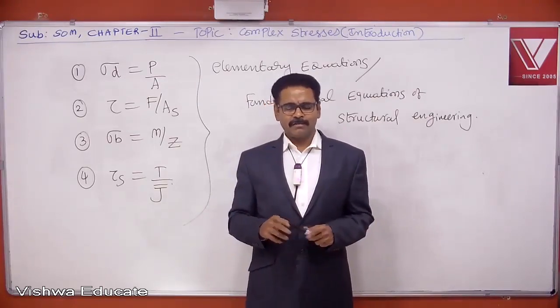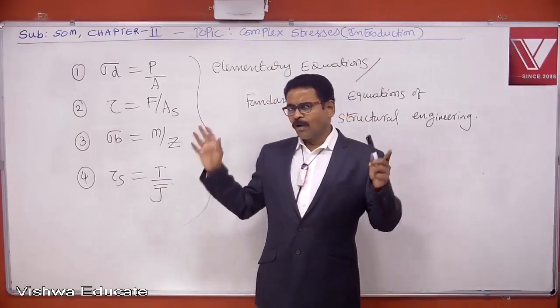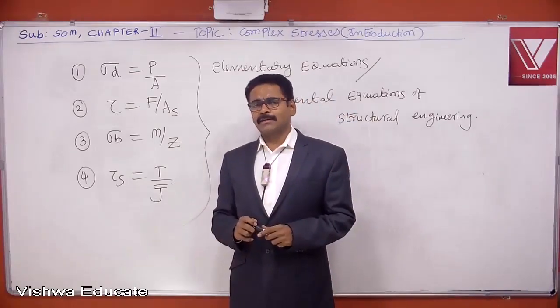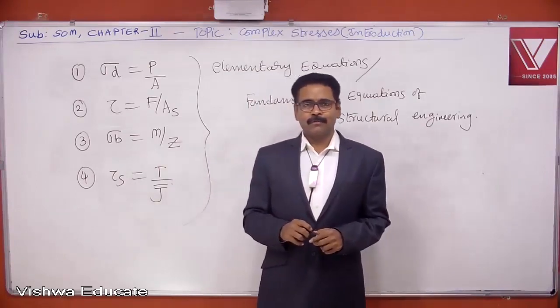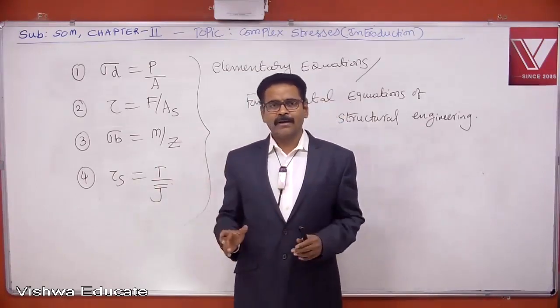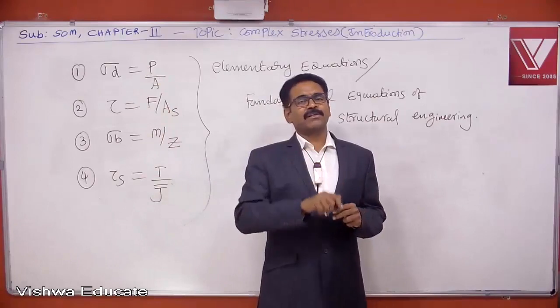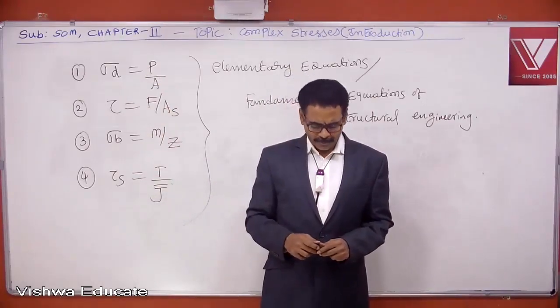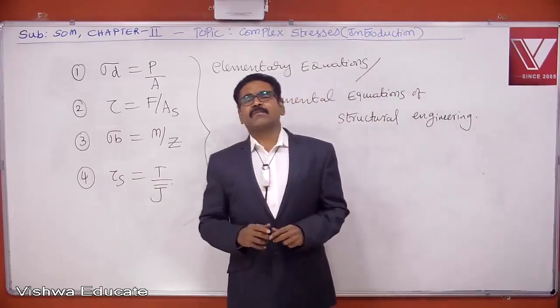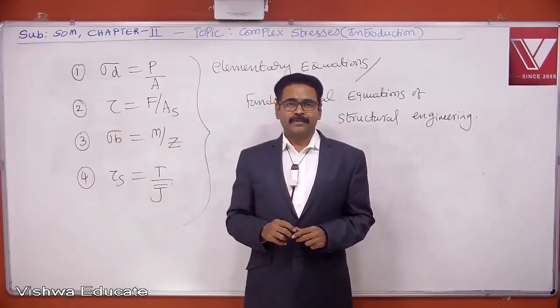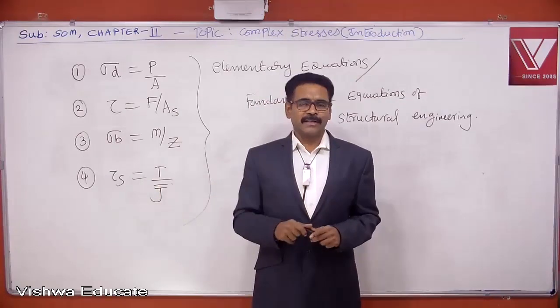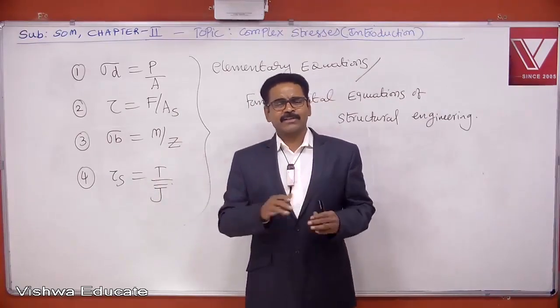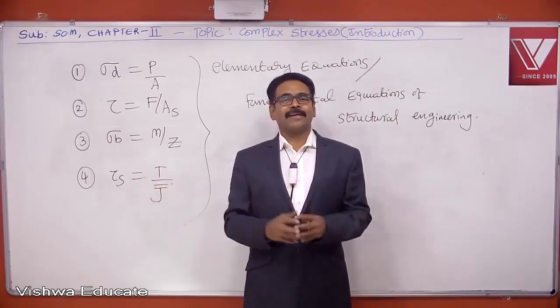Okay? That means while you are designing a brittle structure, you should know or you should find what is maximum normal stress in the structure about a critical point. If that maximum normal stress is less than strength, the structure will not fail.